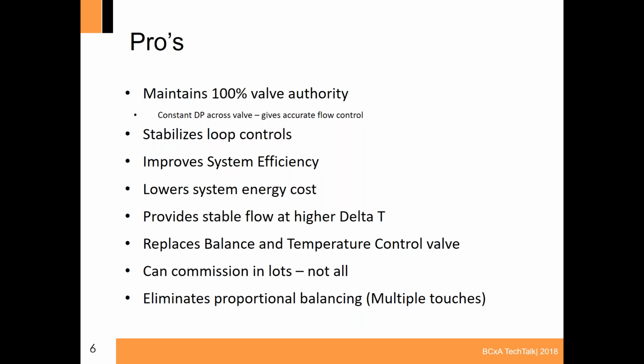Okay? It replaces the balancing and temperature control valve. It's nice not to have additional points of potential leakage. It also reduces the amount of labor required in the field. I have one device that acts as the balancing element and the temperature control valve.